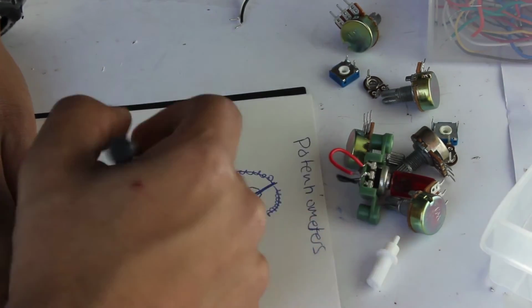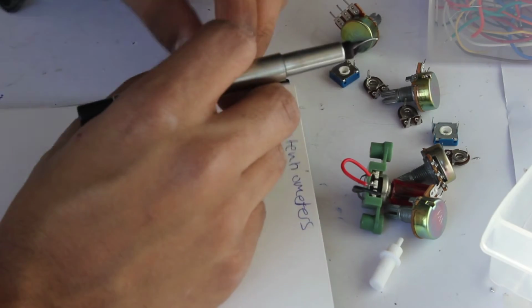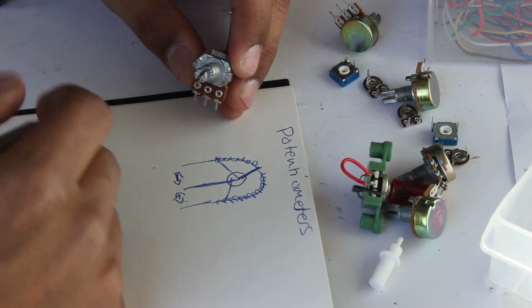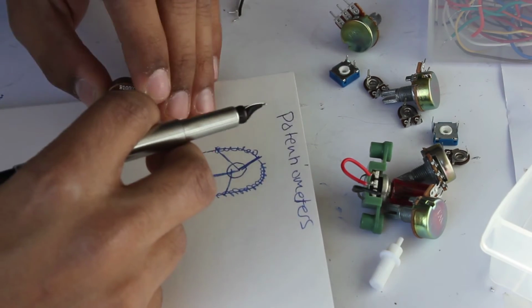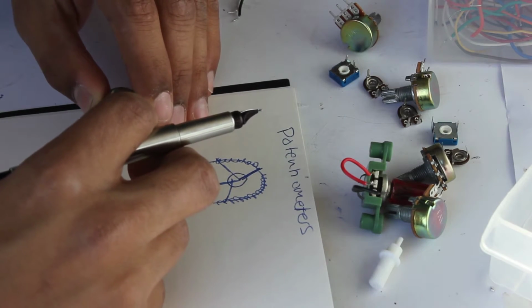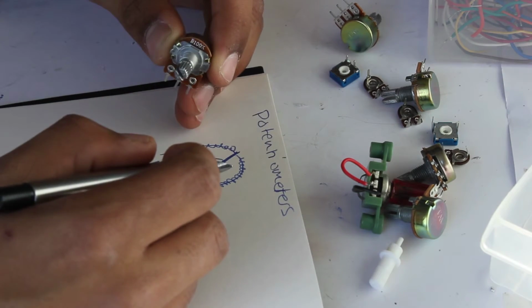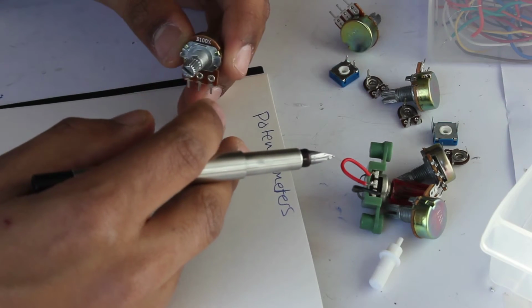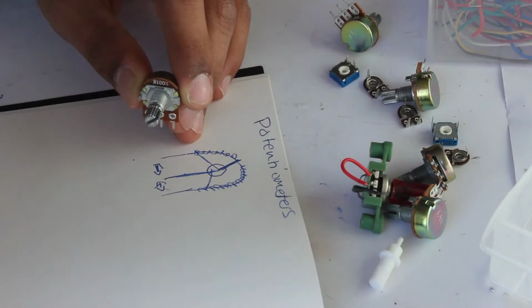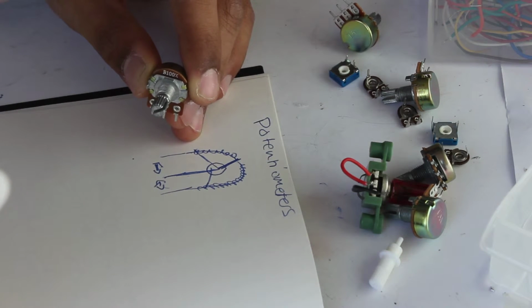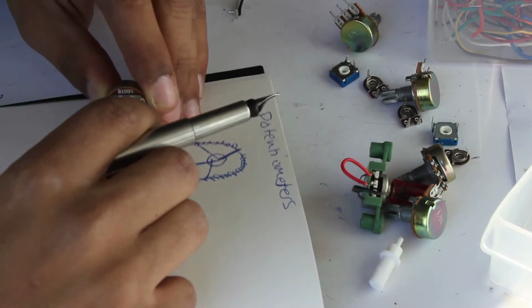Yeah, a good use for potentiometers is controlling a servo motor. So what I'd do is hook this up to an Arduino, say for example, and then hook the Arduino up to a servo motor, and as I turn the dial, the resistance changes in between all 3 pins, and when the Arduino notices that there's a difference in resistance, it will send information to a servo motor. Depending on the code that you put in the Arduino, you can change the angle of the servo motor.